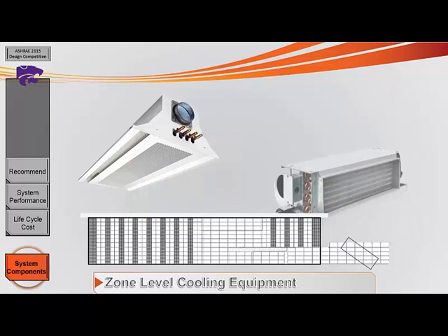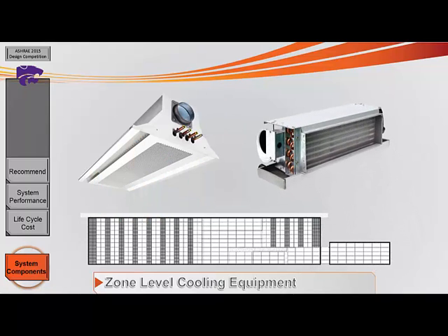Fan coil units will be used in the shop space rather than chilled beams because they contain a filter, allowing them to remove airborne particles from the saws, metalworking equipment, and paint booth. They are also selected because chilled beams are not as effective in spaces with tall ceilings such as special instruction spaces. These units will use chilled and hot water coils to condition the space.